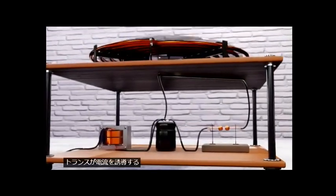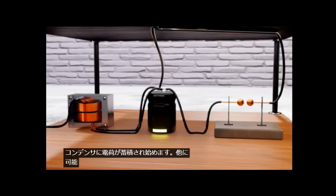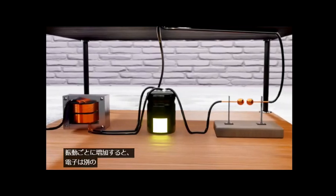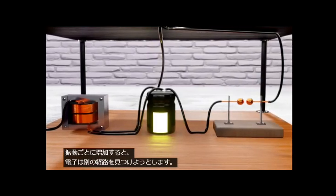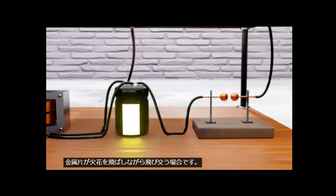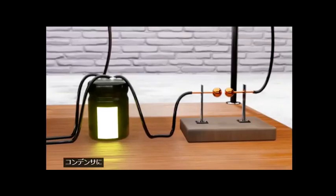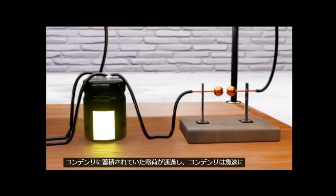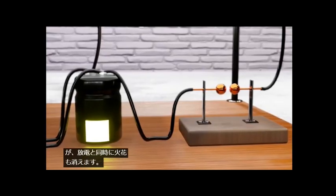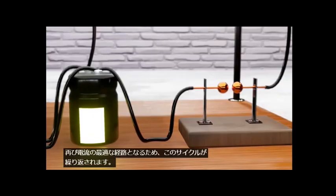When the transformer induces a current, charges begin to accumulate in the capacitor without having any other possible way, but as the source voltage grows with each oscillation, the electrons try to find another path. And the second best option is where the metal pieces are, jumping through them with a spark. This way, the spark will allow the passage of the charges that were accumulating in the capacitor, quickly discharging it. But as soon as they do, the spark will also disappear, because the capacitor will be again the best path for the current, repeating the cycle again.